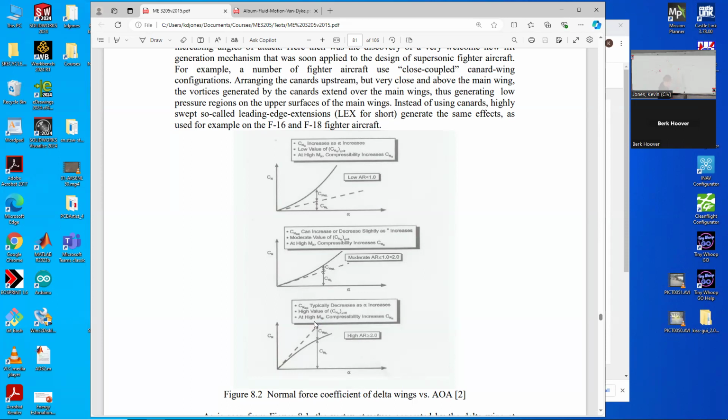turn that corner. And so typically, sharp leading edges are super bad for low speed flight characteristics, unless your wing is super swept, and then whatever stall would normally occur in a 2D section goes away because of the sweep. Most supersonic aircraft that we fly have super sharp leading edges because they work better in supersonic flow, but they're all swept.